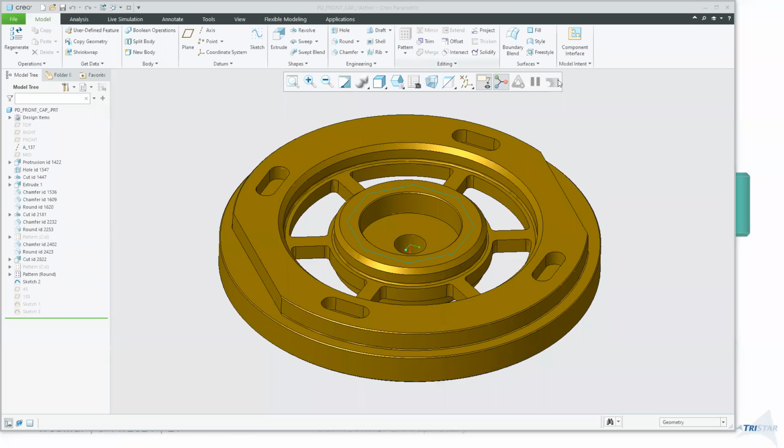There is one in the chat. It says, pattern point quantity will calculate and appear in the hole note, asking that question. Yes, that's correct. It used to be a little bit error prone before, but it will calculate it regardless of how you do it. You could be using a sketched hole like what I was about to show you, or you do the regular pattern, because they use these new tokens. They're calling it hole instance count. It just used to be pattern underscore NO or number that used to be in the format. But yes, it is going to automatically show in the hole note. So you don't have to go and edit it in the drawing, etc.